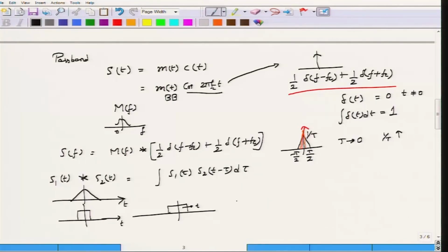Okay. So, you are essentially going to get this signal. This needs to be multiplied pointwise to this S1 of t. So, you multiply these two signals and integrate. You keep doing this for every value of time shift t, and then you will essentially obtain the result of this integration. More details are of course available for you in the signals courses. Please refer to that. If you have forgotten, you can go back and read some signal and system textbook. You will be able to understand what convolution is, or you will be able to recall what convolution is.